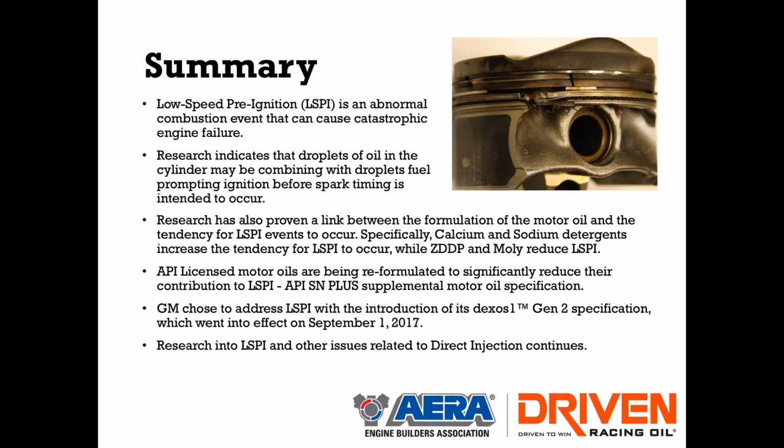But we're not done. We're moving. This is not the end point. I know even on the API side, they're looking towards a new specification coming out in 2020 called GF6. We're at GF5 today. GF6 oils will be built from the ground up to provide LSPI protection. Fortunately, there's products. Obviously, Driven makes a product and GM makes a product with the Dexos 2 that are oils that are built from the ground up already.